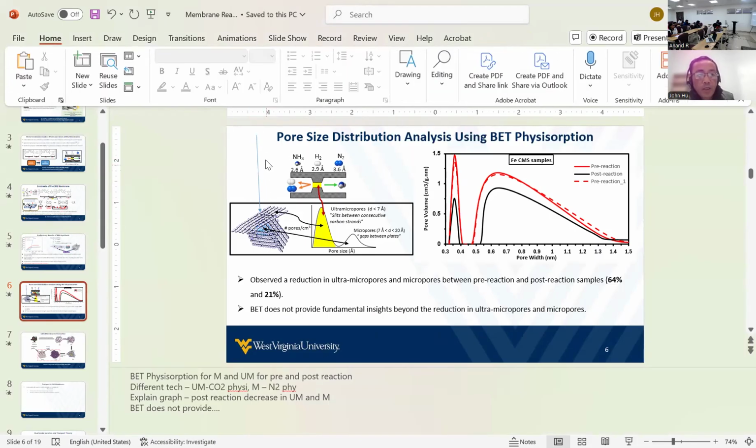So your gas flow passes through all these fibers, and the opening is by design. You can design these fibers and allow the gap, or the penetration, on the fiber. The gap is, let's say, 2.8. Only ammonia comes through, but the 2.9 and 3.6 molecules will stay on one side. So this is the gas flow direction.